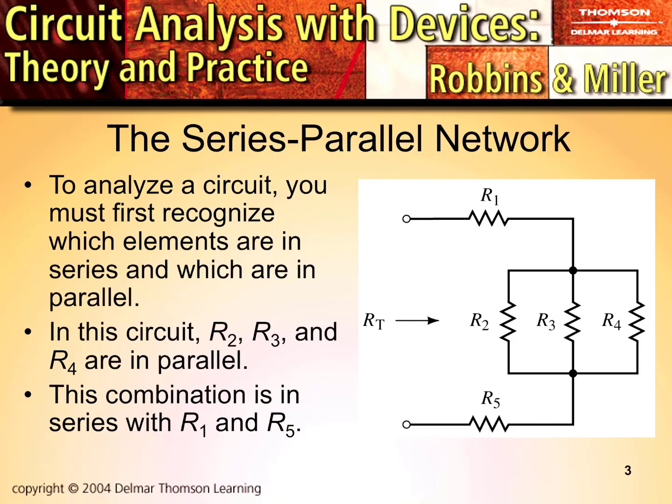If we were to draw some true statements from this example, we can certainly say that we have current flowing, I, and we call that I total because it's the current leaving the source. We know that we are going to have I total returning to the source as the same amount. And we can say that IR1 equals IR5 equals I total.